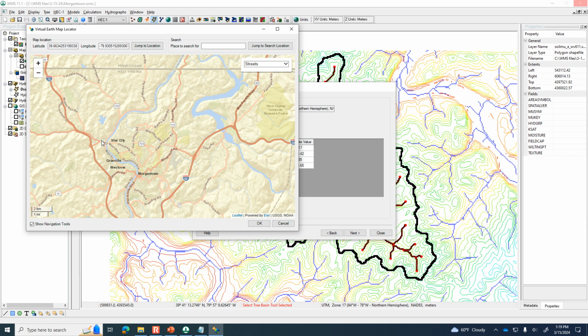then what WMS probably suggested was a 60-meter elevation data resolution, meaning that each one of those cells represents 60 meters by 60 meters square. And so the mesh is more coarse if you're zoomed out. Now you can override that, and it's fine to have the resolution that it suggests. It doesn't end up taking that much more download time.